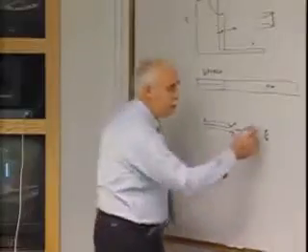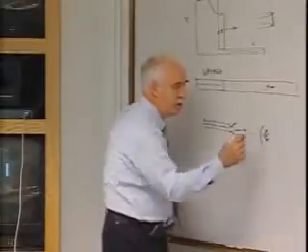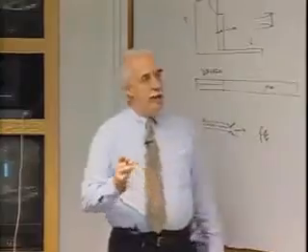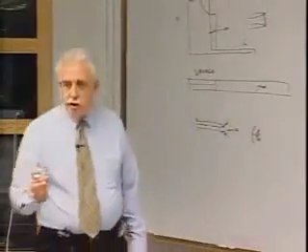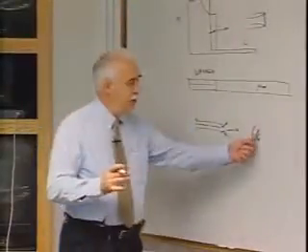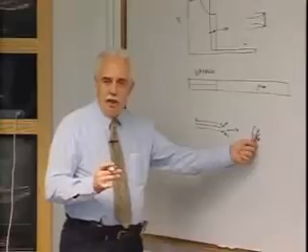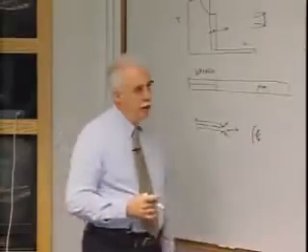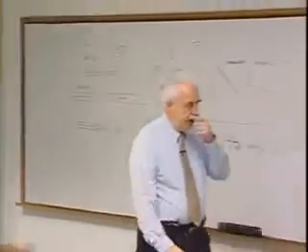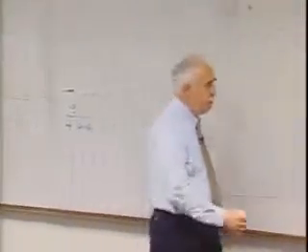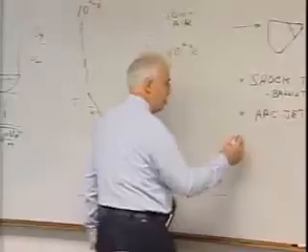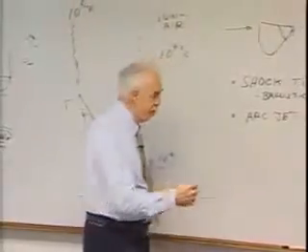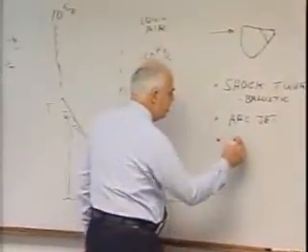But this is where we do research on ablators and research on surface catalysis, which I'll talk about in a little bit, which really can affect the heating, particularly on a shuttle, and I'll show you some results there. But in any event, the arc jet is the other major facility from a TPS material standpoint, TPS being thermal protection system.